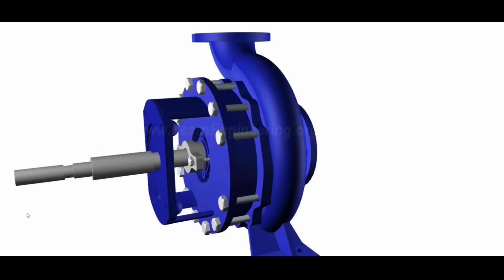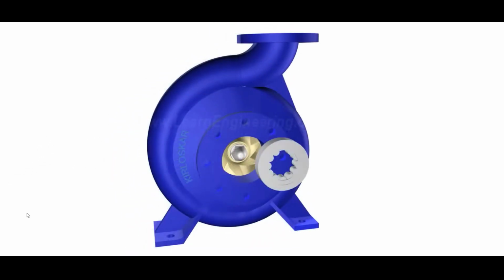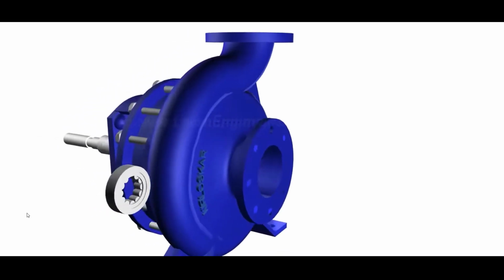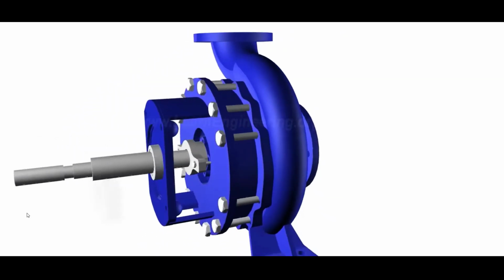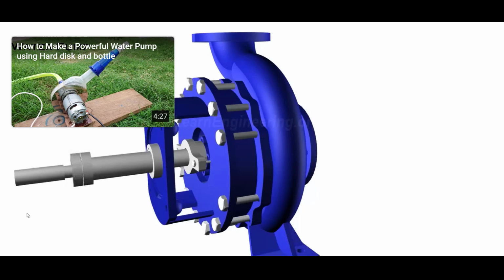The impeller is mounted on bearings. But at the suction side of the impeller, it is not advisable to fit a bearing since it will block the flow. So bearings have to be fitted at the other end. This means the impeller is mounted like a cantilever. For high flow rate pumps, a bearing housing with cooling oil is necessary for improving the life of bearings.